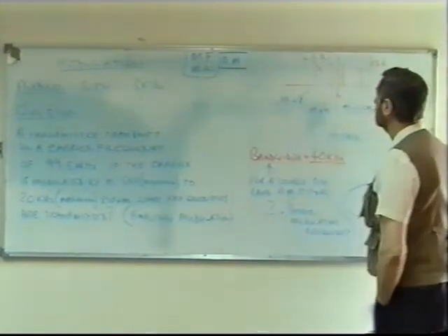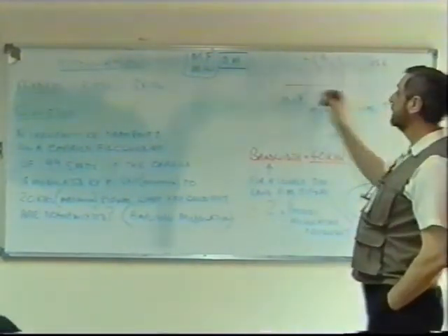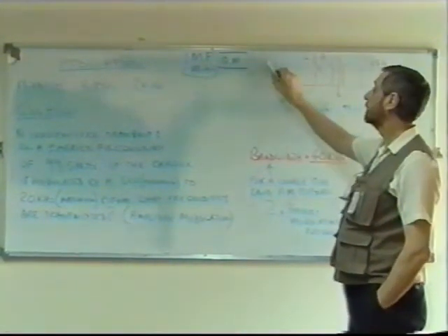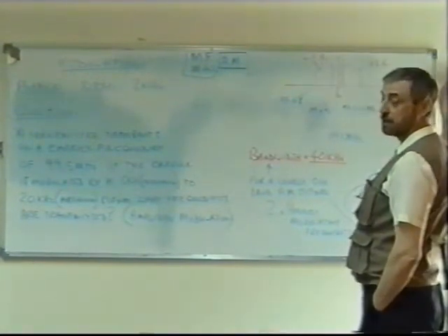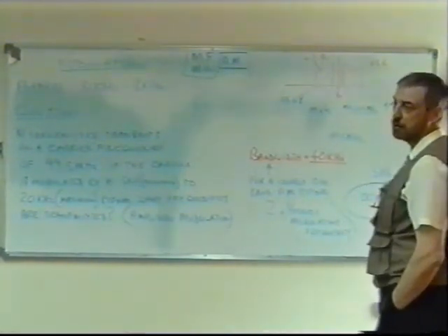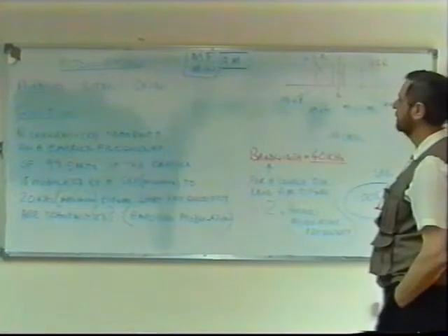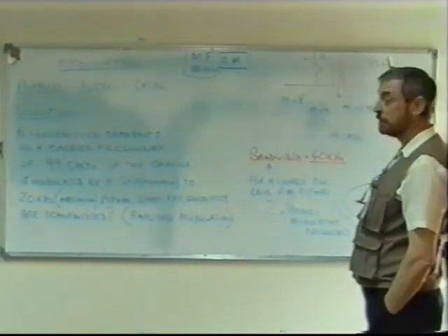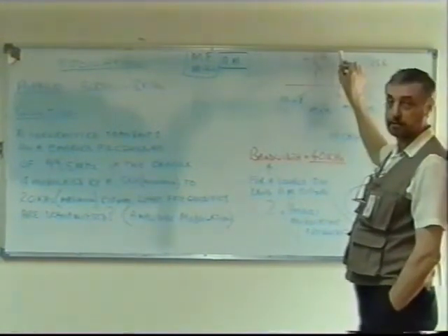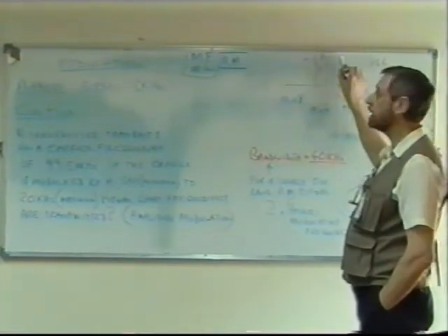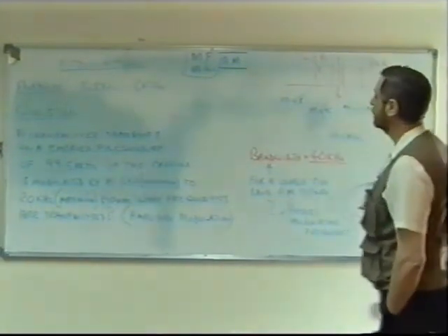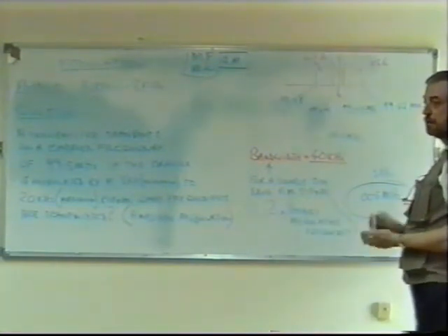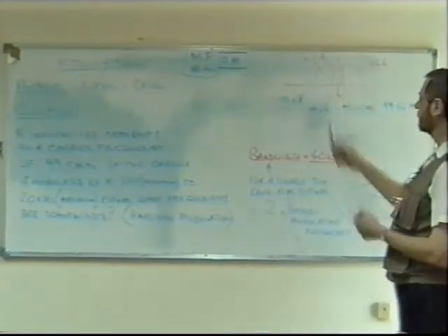That's the reason why, when you tune your radio up and down the band, you get different signals coming in. But there should be only one at a time. Occasionally you might get some interference, but it shouldn't happen. You should only receive one signal at a time. Each signal will be modulated like this, more or less the same band of frequencies, but at a different carrier. And that's what you're doing when you're tuning your radio. You're selecting, by using a filter, a different set of frequencies.